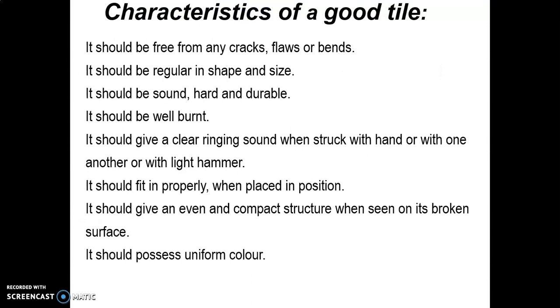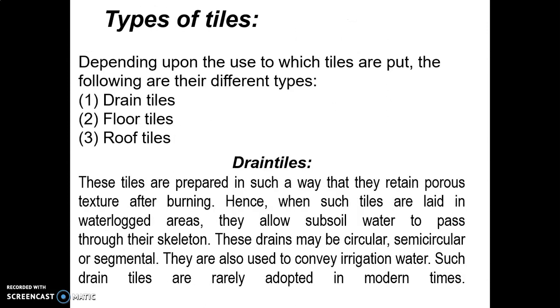Characteristics of good tile. It should be free from any cracks, flaws or bends. It should be regular in shape and size. It should be sound, hard and durable. It should be well burnt. It should give a clear ringing sound when struck with hand or with one another or with light hammer. It should fit in properly when placed in position. It should give an even and compact structure when seen on its broken surface. It should possess uniform color.